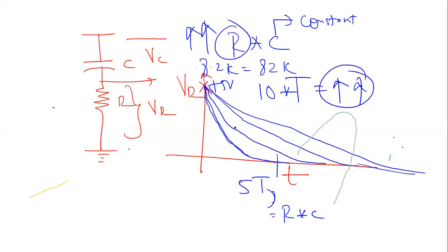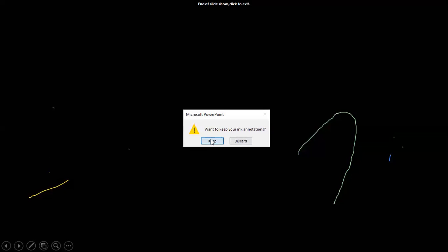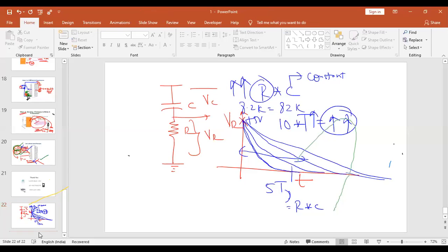So essentially, what am I doing? By increasing this time constant, I am increasing the duration for which the circuit remains in reset. If you want to understand it more clearly, I will draw another graph and show you, so that it will become much clearer for you.